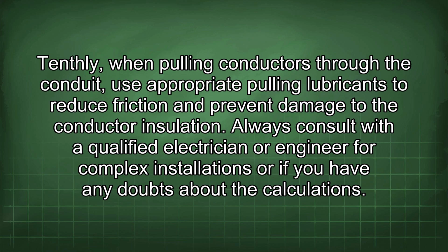Tenthly, when pulling conductors through the conduit, use appropriate pulling lubricants to reduce friction and prevent damage to the conductor insulation. Always consult with a qualified electrician or engineer for complex installations or if you have any doubts about the calculations.